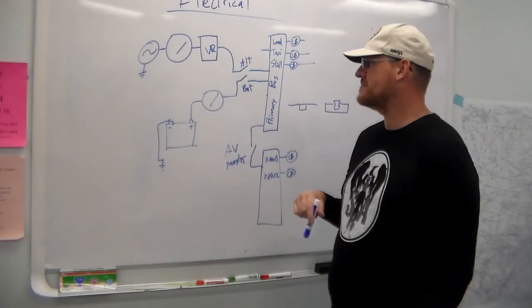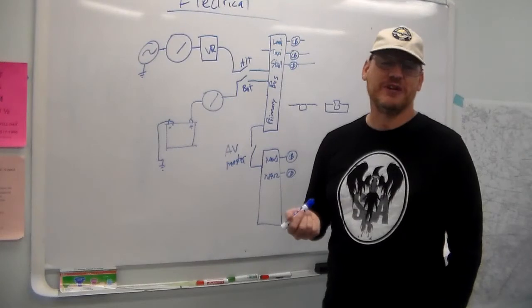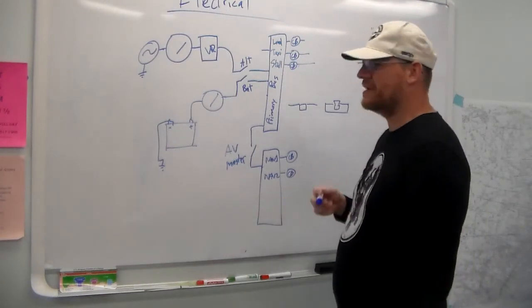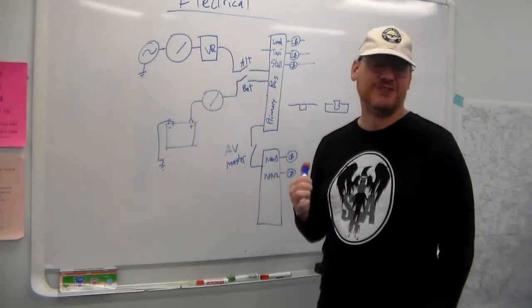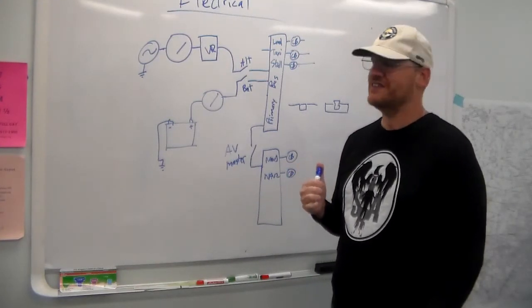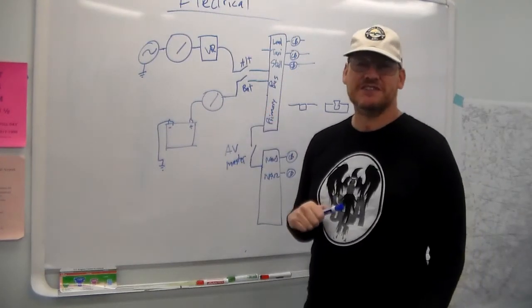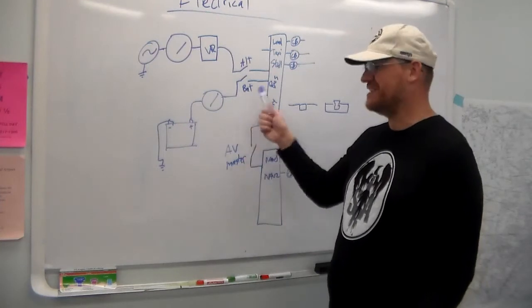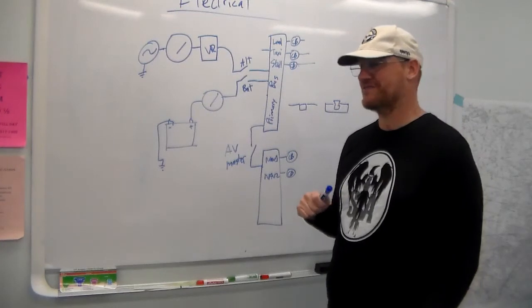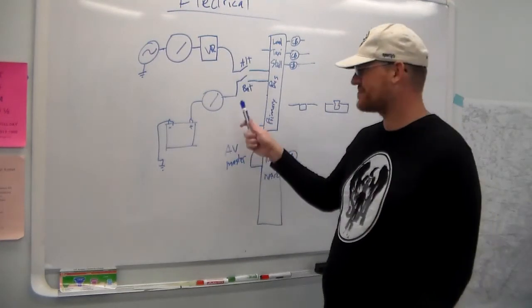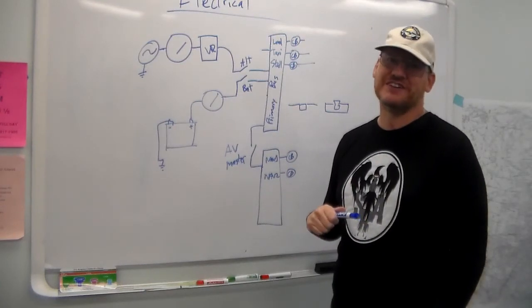Well, sometimes you'll see an AC breaker, an alternator breaker, and some aircraft like the Alaris that I used to fly actually have an alternator field switch. Now in the case of that aircraft, the master, essentially the battery master if you will, is a circuit breaker. Every switch in the Alaris is actually a circuit breaker. So it's a circuit breaker switch. Right next to it is the alt field breaker.